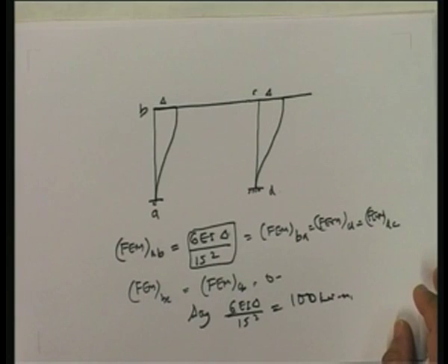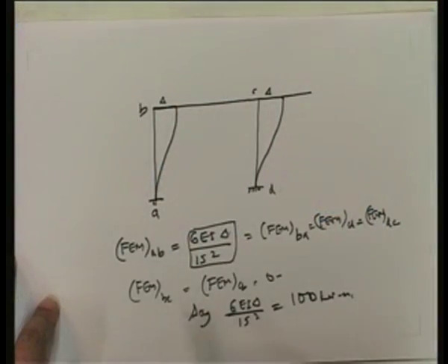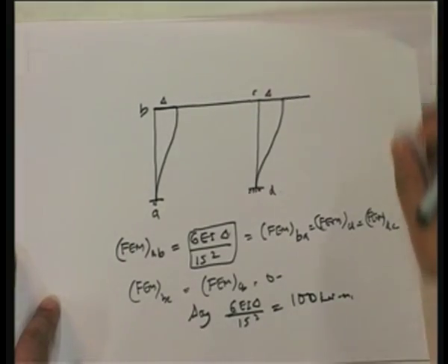So that's why, when you look at the sway problem, what do you actually do? You put any one of them equal to 100, and you can compute all other fixed end moments automatically. In this particular case, since all the moments are equal to 100, we will get that all fixed end moments are equal to 100. That's incidental in this particular case. Okay. So now the next step is to find out the distribution. Distribution factors remain the same. Distribution factors are what they are originally.